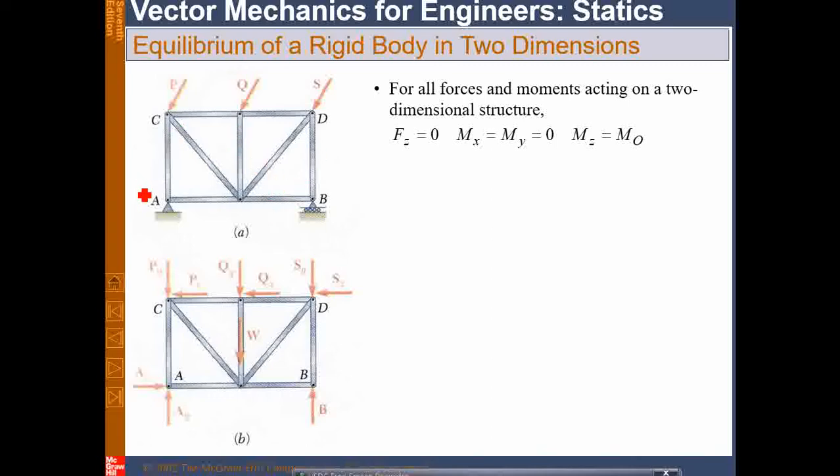They all carry these trusses because these are the different members of the trusses, and they can take a very high amount of loads. So they may be fixed at one location and may be allowed to rotate, or sorry, allowed to move along the other location. Usually this kind of restriction is done. You may be surprised to know that some horizontal movement is actually beneficial